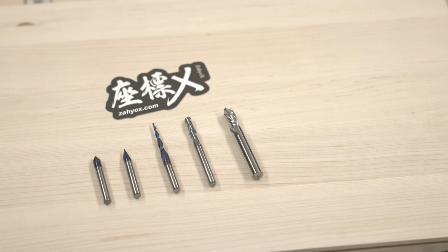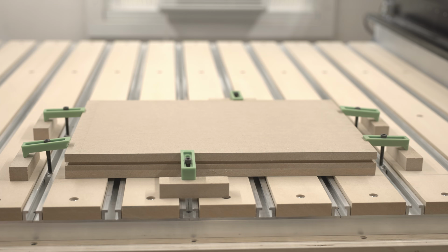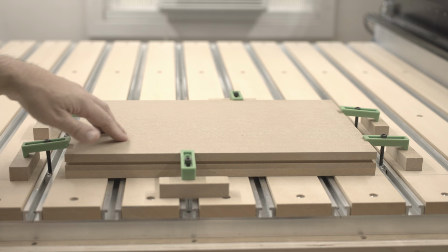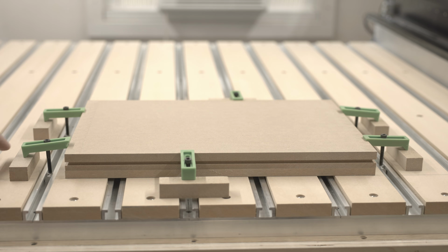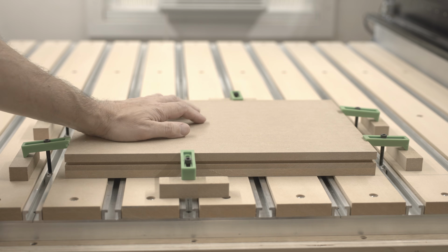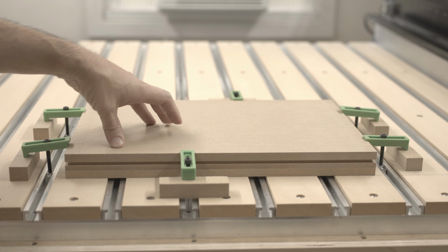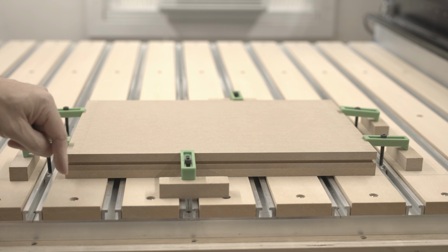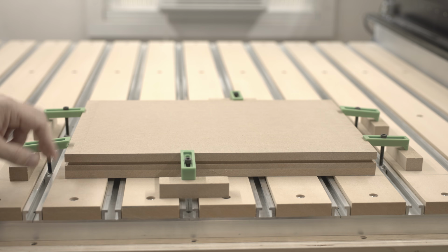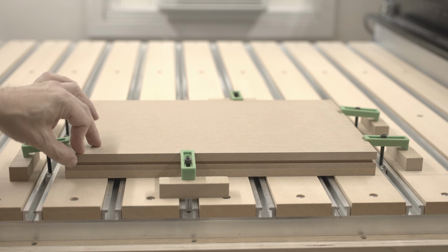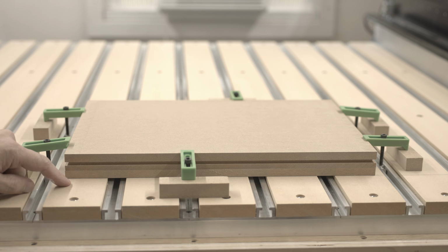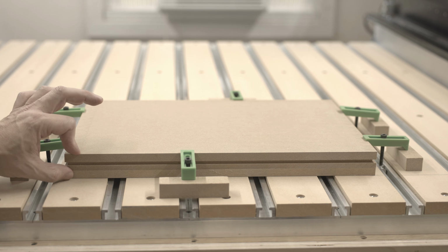All right, so now let me show you the setup and we'll get started carving. Okay everyone, I just wanted to go over my setup on the machine before I start carving. This is very important. This is what I have set up for my base to mount my board onto. Because I raised my machine 3 inches, I can't get really low to the surface of the table without putting a spacer on it or using a collet extender. So I chose to go with the spacer on this one. I've got a 1.5 inch buildup on the bottom here.